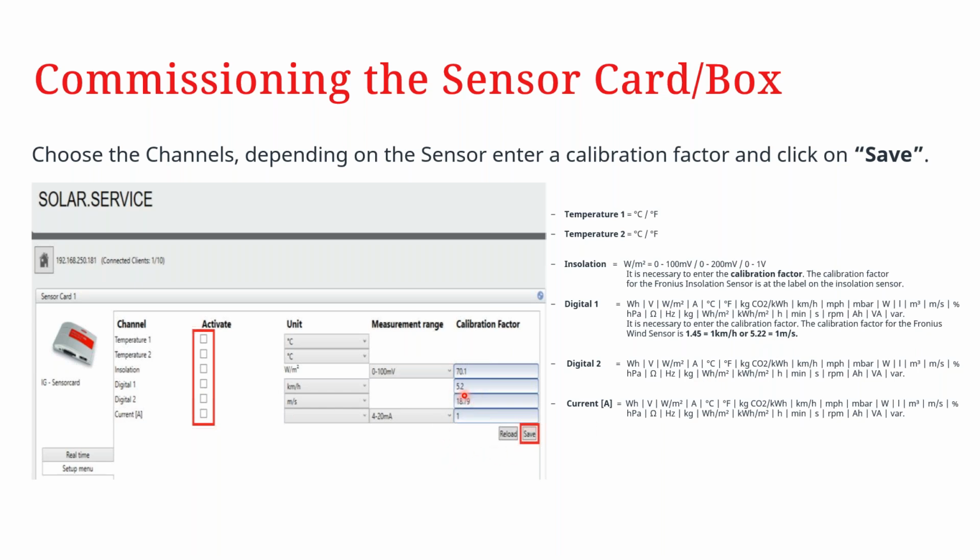As you can see in this case as selected. So same variables can be measured across the digital and the current output. So once you've made your selections, and for the current, just to note here, I think David has mentioned it already, you have 2 measurement ranges, that is 0 to 20 milliamp or 4 to 20 milliamps. So select whichever is your preference.